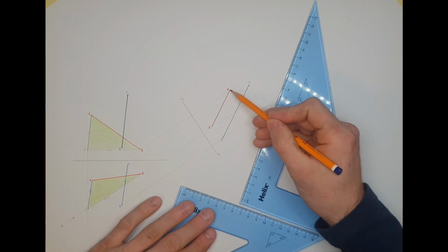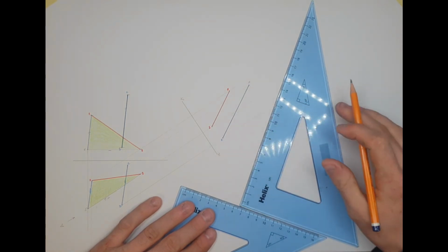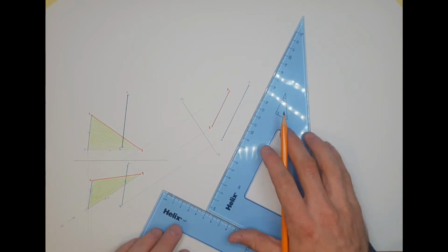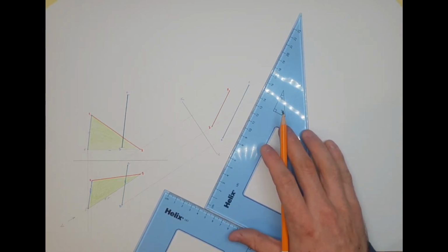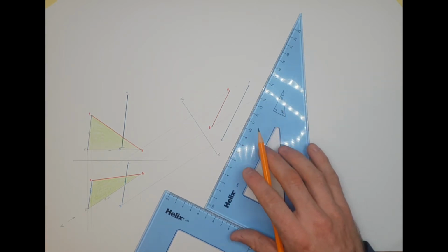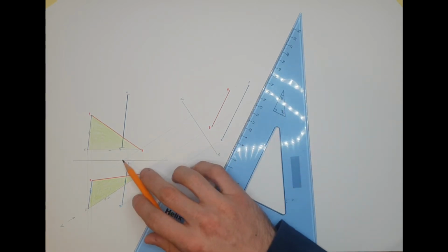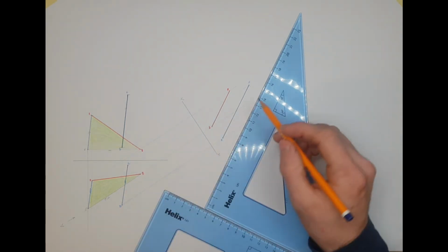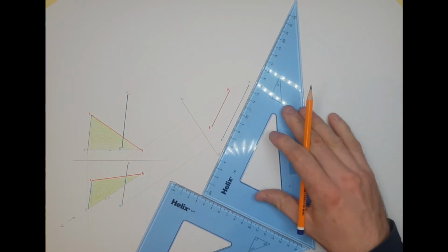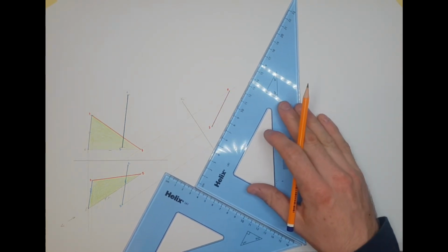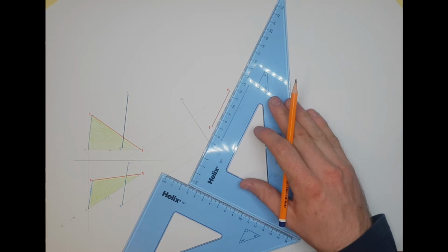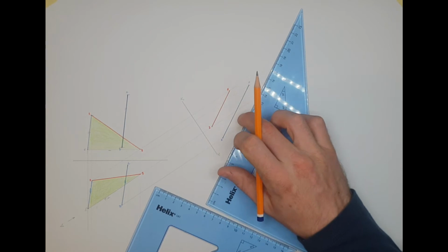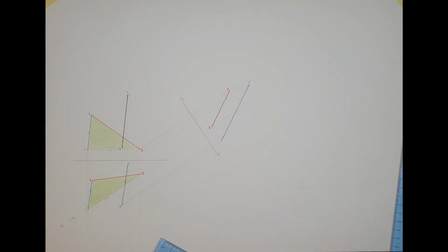I don't like to draw the two lines first and then see how accurate it was after, when you realize that the lines don't look parallel. So you want to make sure that you check them first of all, and if need be, you might have to go back and check your setting of your compass. Maybe you went a little bit too high on C, maybe you didn't project exactly from point C, and a few mil here will mean that one line is not parallel to the other, and that's going to create a bit of a problem going forward. So make sure you check as you go along. Make the check now instead of realizing in 3 or 4 steps' time.